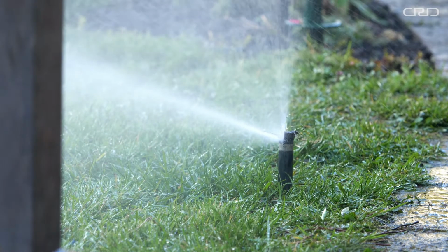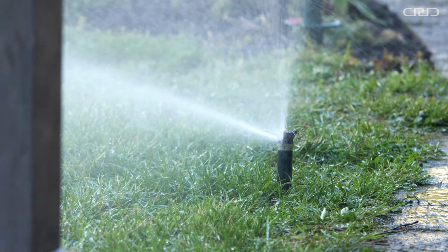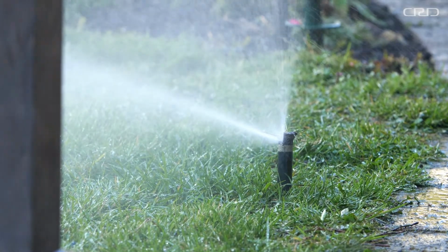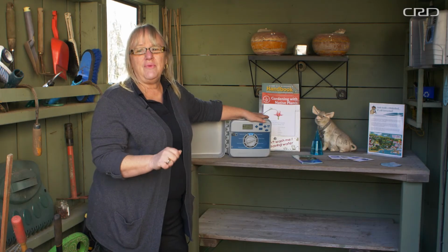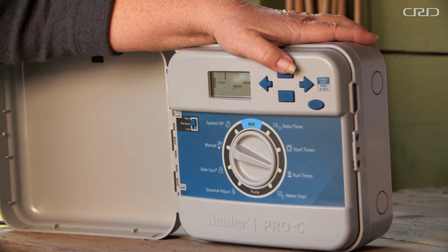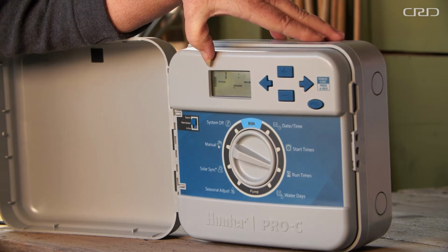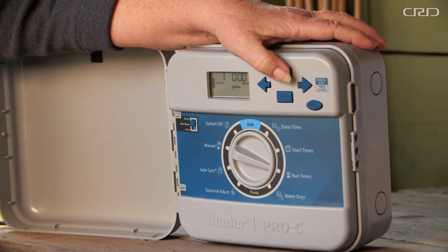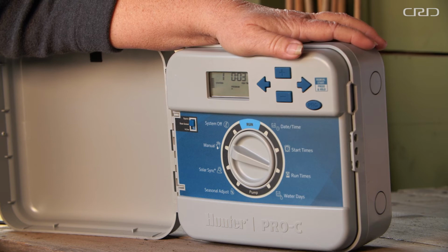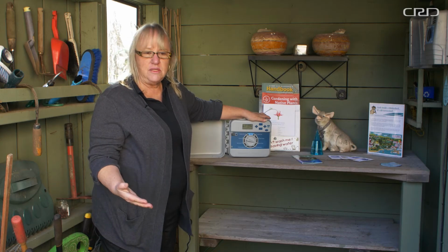Under program A, for our lawns, first thing we need to do is tell it when we want that program to start. So I turn my dial to my run times, and on each station it's going to have my station indicator. It's going to say station 1. I use my up and down arrows to set how long I want it to operate. So if I set it for 10 minutes,